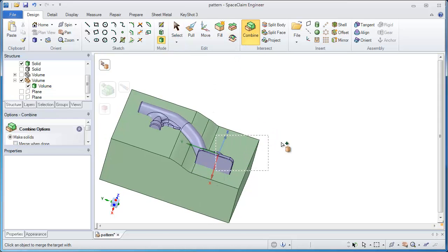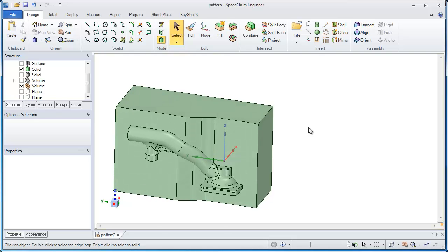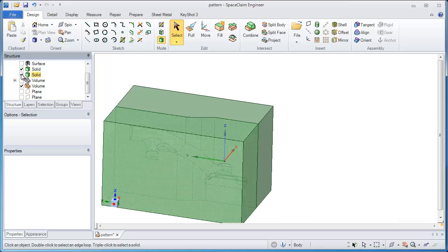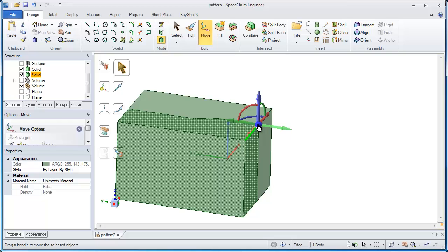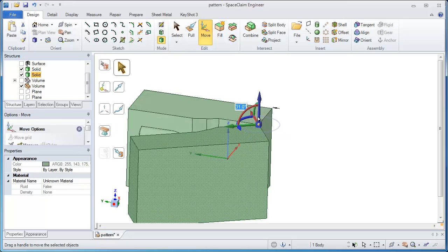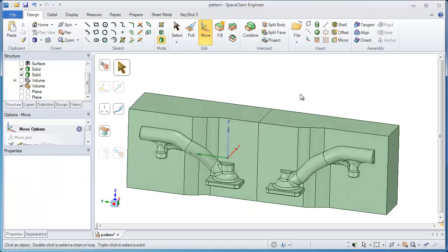The important thing I wanted to show you was creating the parting surface, but also how easy it is to use the newly created geometry and the cut-up geometry to start making the different halves of your pattern. Last thing I might do, very last thing, is go ahead and rotate this around maybe 180 degrees. Easy to put precision in there. Not everything is dynamic, and so you can see both halves put right next to each other.